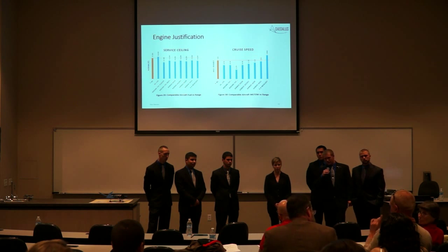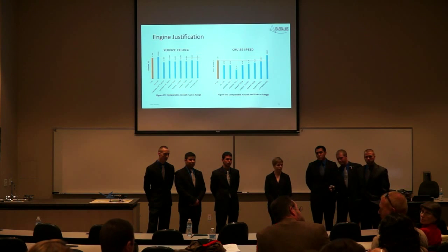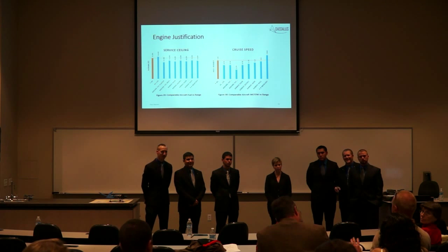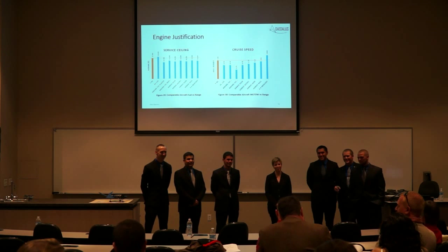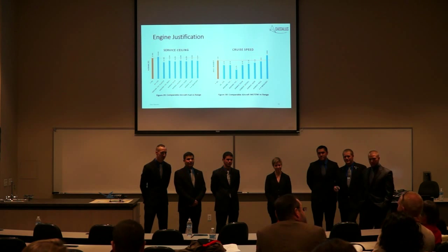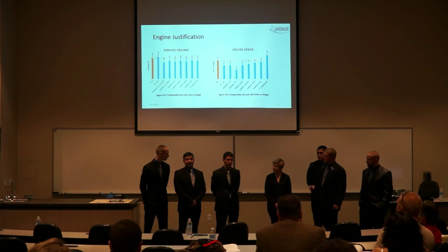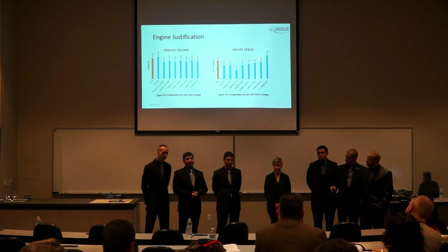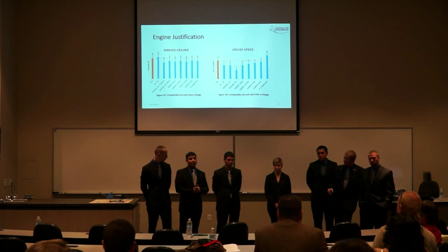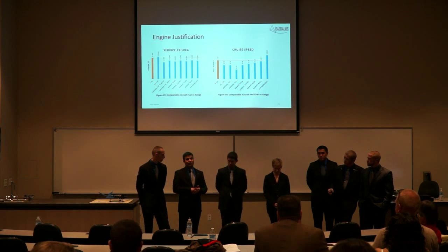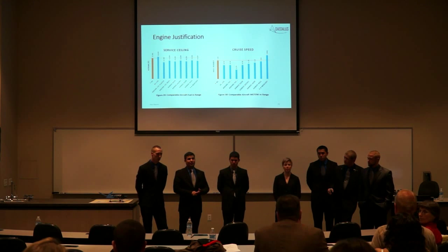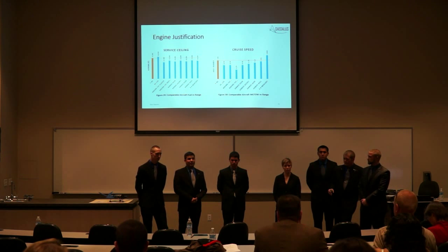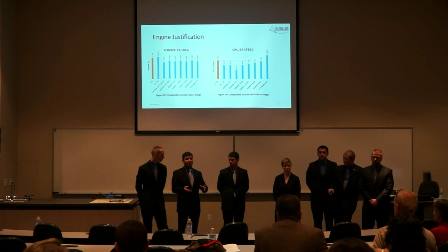Okay, I have one last brief question, passed on to Professor Chrysler, which is, I know that all professional pilots make perfect landings, and that's probably so for the Air Force pilots. What are the side loads on those landing gears? No side loads have been calculated. I was following preliminary design for the landing gear. Side loads are not part of it, at least not in Raymer's or Roskam's book. So that will be further developed, as well as all the mechanisms for retracting the landing gear into the doors, and as well the shock absorber. Shock absorber is still in a preliminary phase.